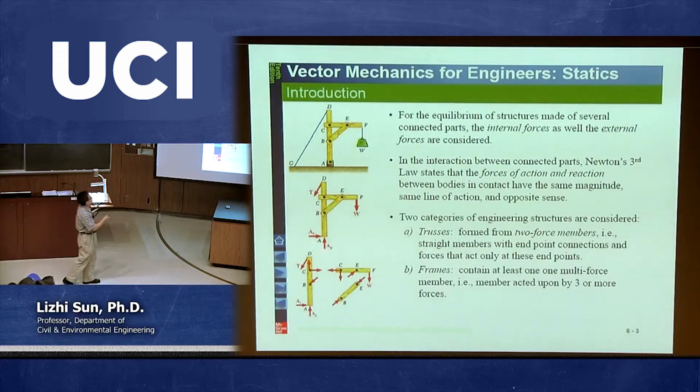For example, we call AX and AY. And then finally, we see there's a cable connecting between one point in the rigid body D and also another point with a support, with a ground. So then obviously we need to cut somewhere here or anywhere, and then correspondingly we give this cable force. So this is what we call the free body diagram we introduced in chapter 4.